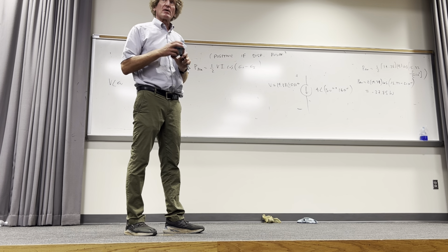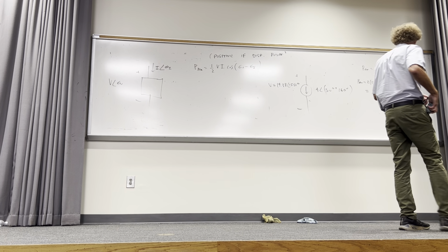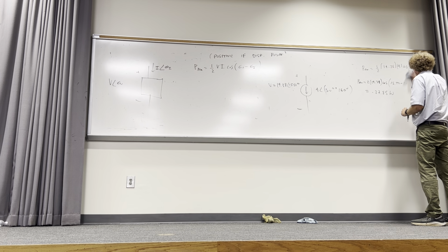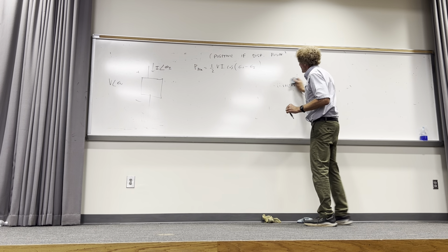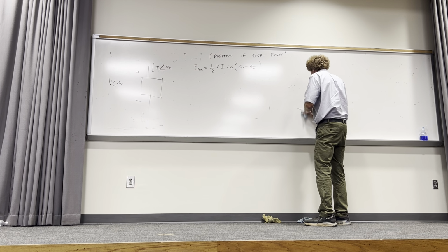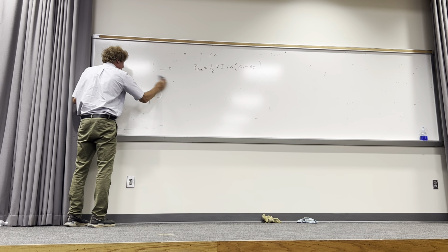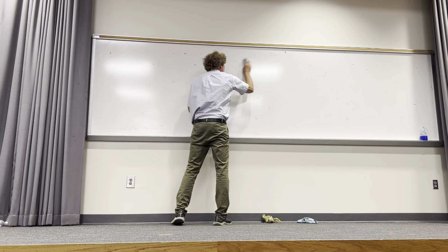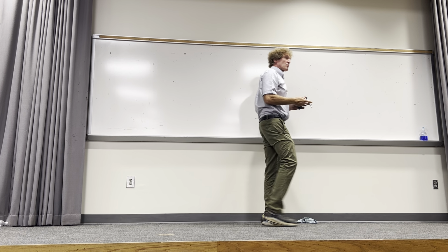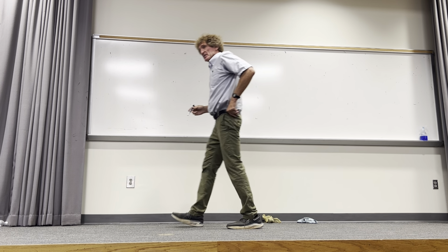What I want to show you is one thing called RMS values of voltage, or anything. It's called the root mean square. Probably in your other engineering courses, they have something equated to this. The real reason we're doing this is because the RMS value of voltage is very useful to get an idea of the power, or the real value of the signal in terms of supplying power, because you can have an enormous amount of peak voltage, but it only lasts for an instant. So the root mean square value, or VRMS, can be very small. It's the same with the current. I just want to define this for you.